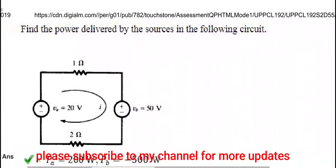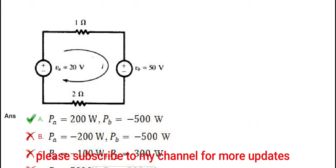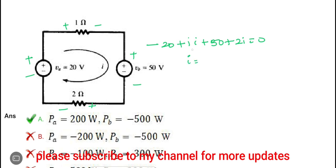Next question. Now find the power delivered by the source in the following circuit. As we see, we'll apply KVL in this loop. If we apply KVL in this loop, starting from here, minus 20 plus 1 into I plus 50 plus 2 into I is equal to 0. Now what is I? 3I is equal to minus 30, so I is minus 30 by 3, which is minus 10 amperes, the current flowing. As we know, the current is flowing in this direction, so the source is going to deliver negative power.